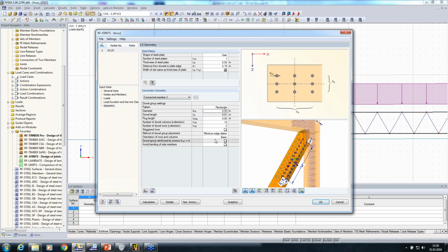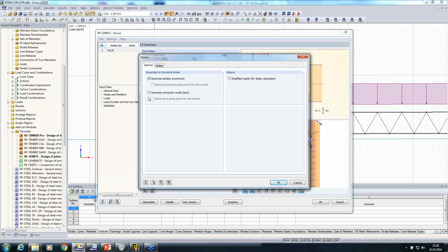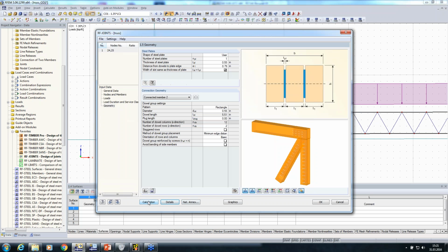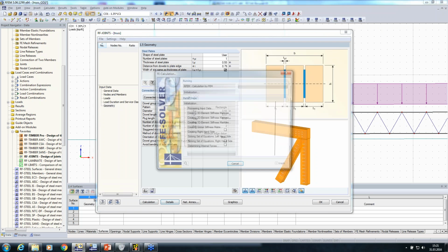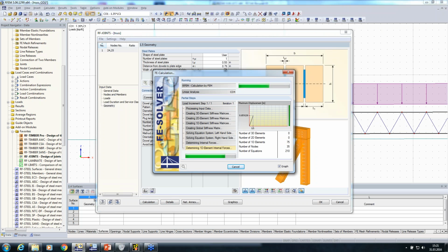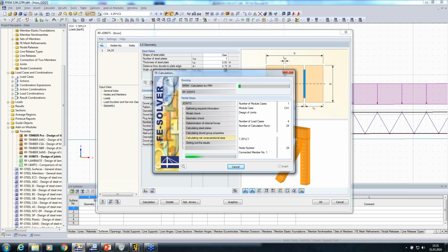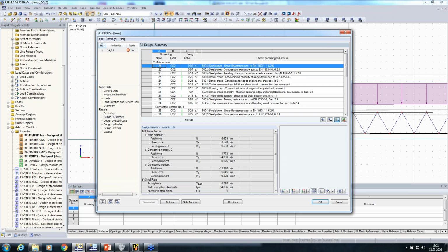In practice it is probably more common to use a user-defined distance here and to make a bigger surface you can attach with the dowels. But as I said, for now, that should be enough. Now I can tell the module to export the stiffness to RFEM and make a design with an iterative design process by changing the stiffness outside and calculating the forces again inside.